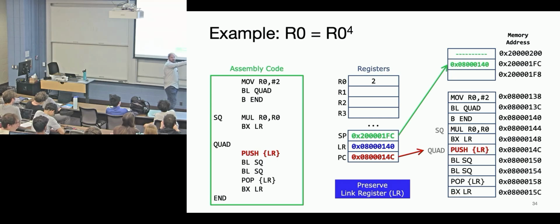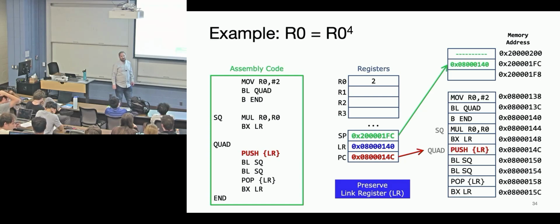So basically, we said there was some value in memory. You could put it back in the link register, but you want to branch. So just place it in a different location. When it says PC, it's not doing anything with the current value of PC. It's taking the thing from the stack, which is the next return address, and putting it directly into the program counter, forcing a branch. Okay, I see. It's just that the names are allowed to be different. It doesn't see, oh, I need to find the PC. It just sees the next address on the stack. Yes, the programmer knew that the thing in the stack was the next address it was supposed to go to, so it just directly put it into the PC.